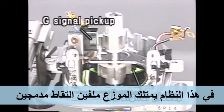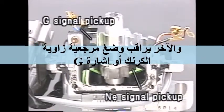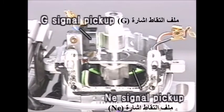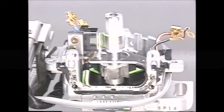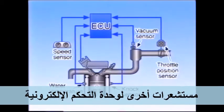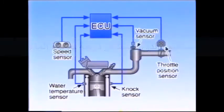In ESA, the distributor has two integrated pickup coils, one of which generates an engine speed, or NE signal, and the other a crank angle reference position, or G signal. While the engine is running, these signals are continually transmitted to the ECU. In case of the D-type EFI engine, other sensors are provided for the ECU, such as the vacuum sensor, throttle position sensor, knock sensor, water temperature sensor, and vehicle speed sensor.